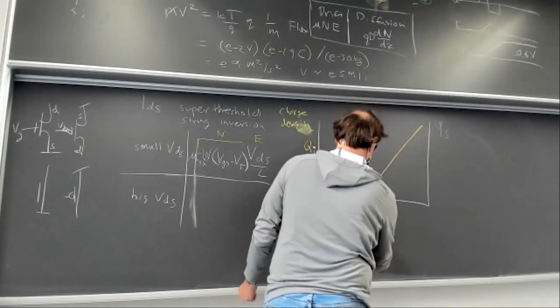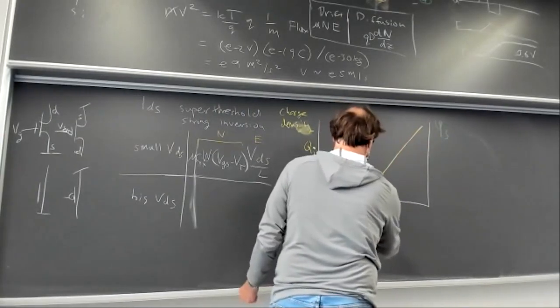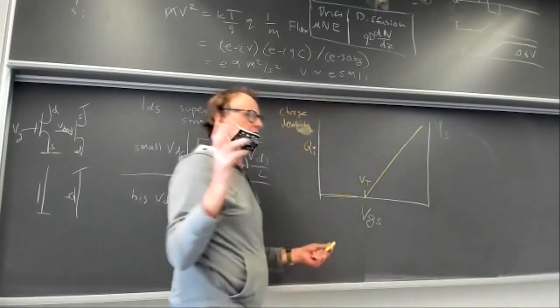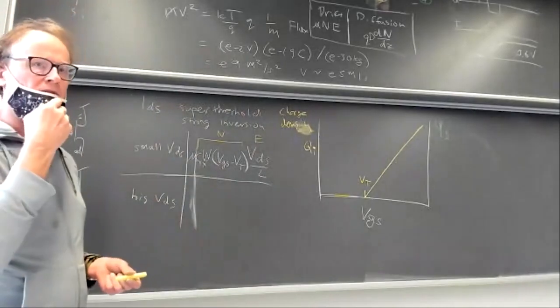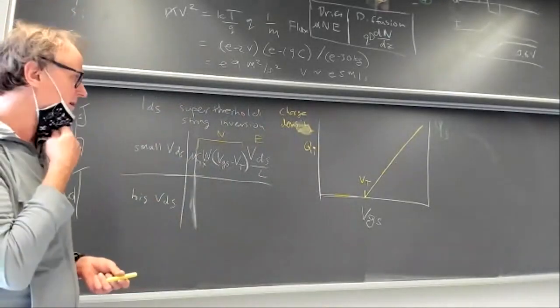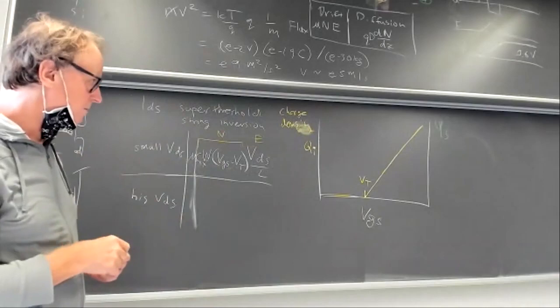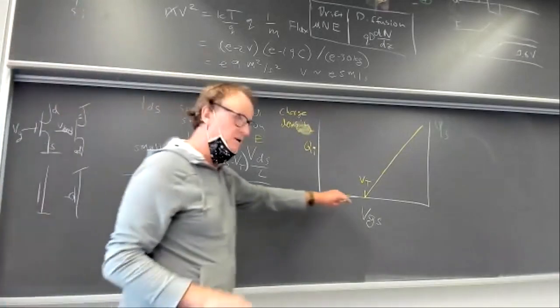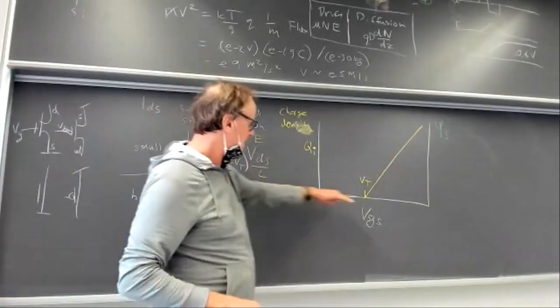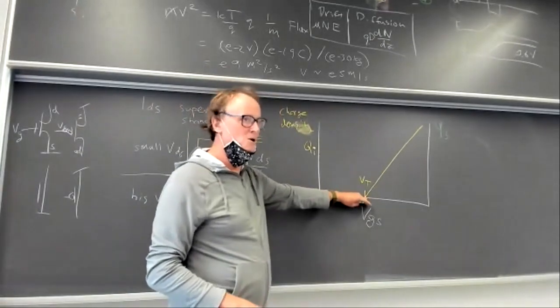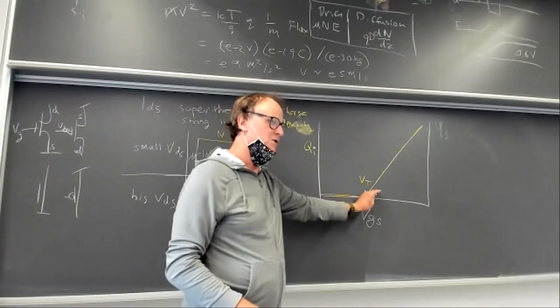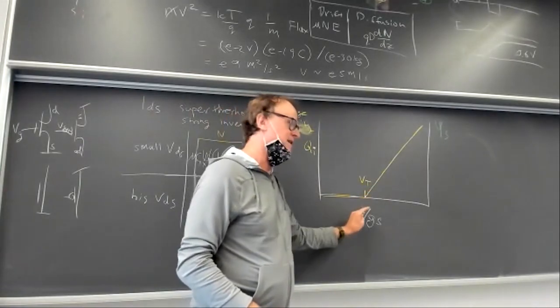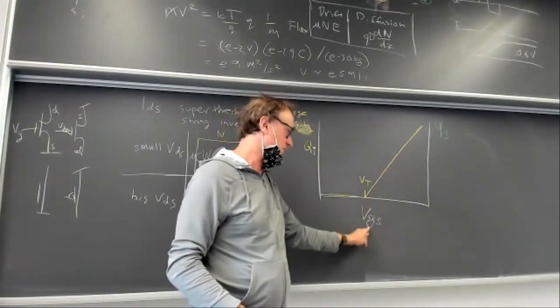Okay, and so this voltage right here is the so-called magic threshold voltage. Threshold voltage is around 0.5 volts, 0.8 volts, around a fraction of a volt, several hundred millivolts. So that's the mobile charge density; it's zero for the purpose of this equation. When you're below threshold, there's no mobile charge in the channel. And when you go above threshold, the charge density in the channel just increases linearly with the voltage above threshold.